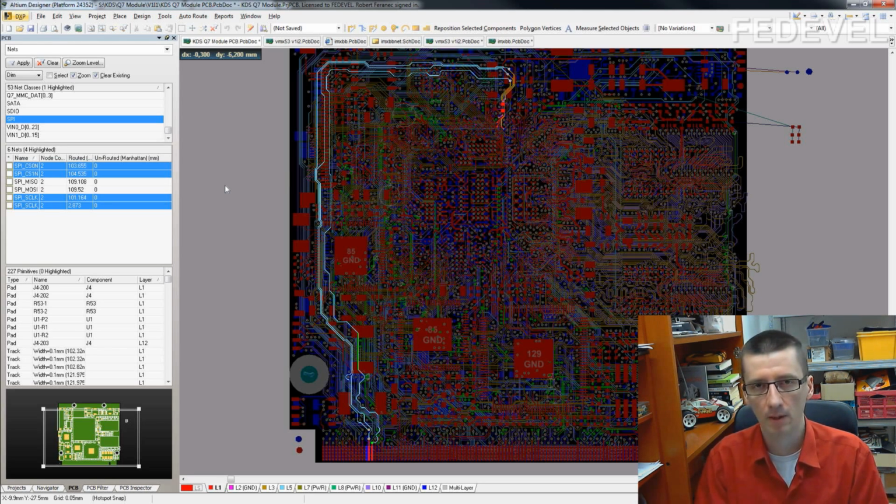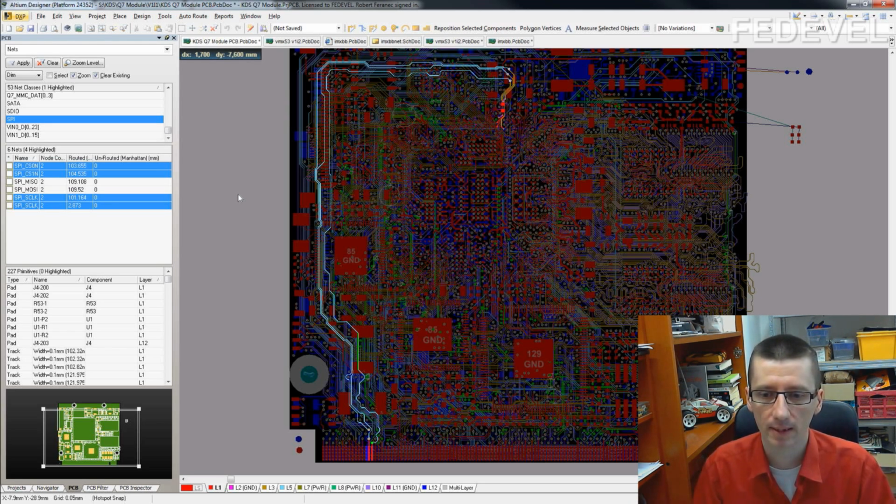But most of the time, when everything is correctly planned, you can just do it at the end and it fits perfectly. Also, it depends how many layers you can use for power planes. So if you are very limited with power layers, consider doing some kind of basic connection at the beginning of the layout, just after the placement. But only very rough connections. You don't have to connect every power pin. You understand what I'm speaking about.